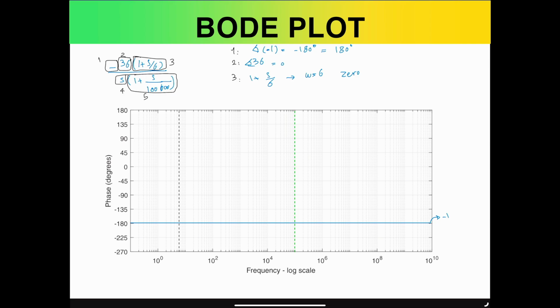I have already demonstrated the first critical point at the frequency of 6. And we know that since this is phase, the phase is going to be 45 degrees at that point. So let's call it 45 degrees with a dot. And then we know that 1 decade above and 1 decade below that, we're going to have a phase of positive 90 degrees and 0 degrees respectively. So it'll be something like this in general. 1 decade after that, we have 45 degrees higher, and 1 decade before that, we have a 45 degrees lower angle in phase. So you're almost dealing with these two values roughly, and we can draw the rest of the diagram like this.